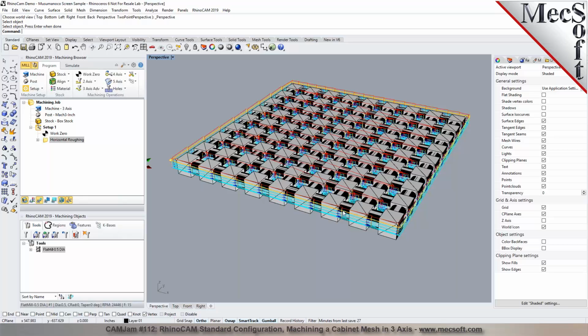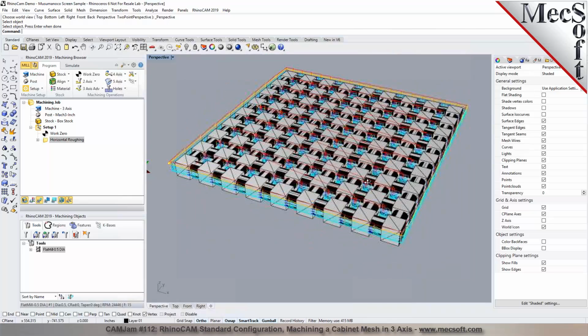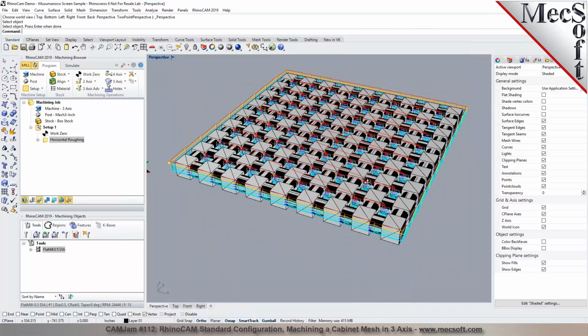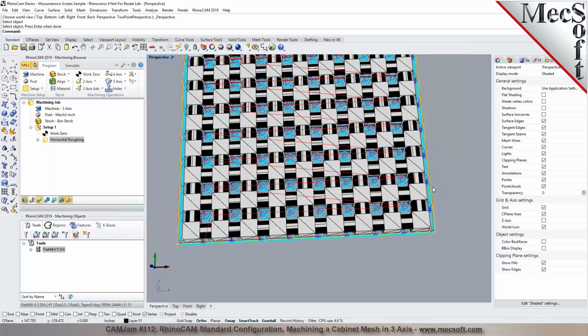Okay, if you had just curves, then you would have to select the curves, and you would have to control the depths and everything. But since you already have a mesh, it already knows where to go and where the part is and where the stock is. And then the mesh also automatically comes in from the STL file from SketchUp. Yep. Correct? Oh wow. Okay. Cool. And you see that we were contained, so we got good coverage around the corners and everything.